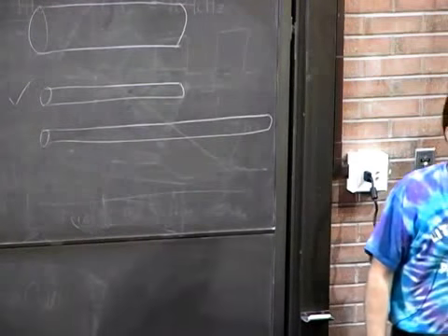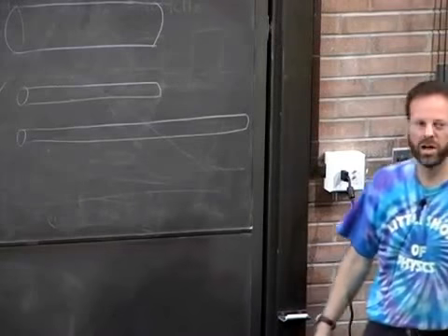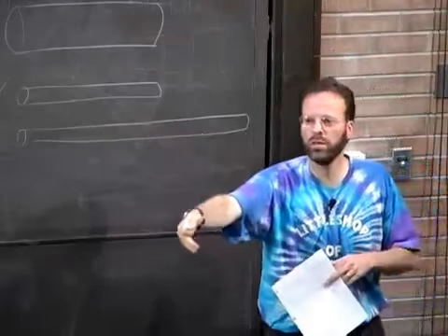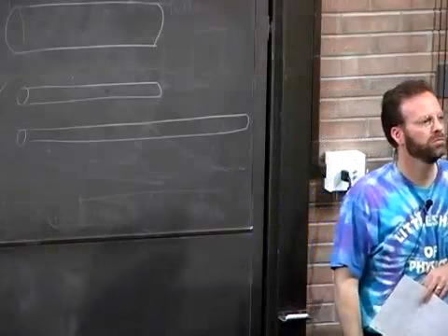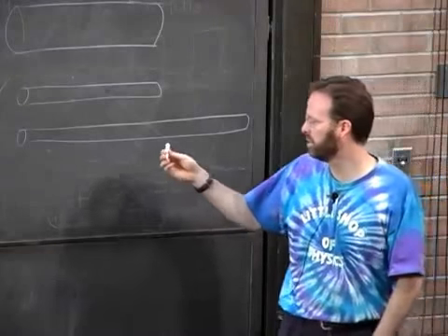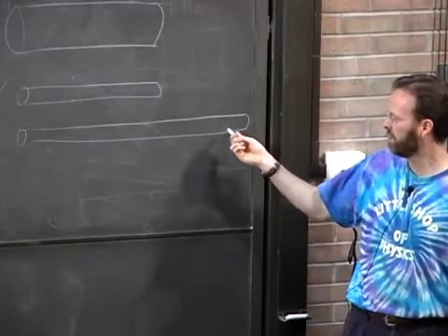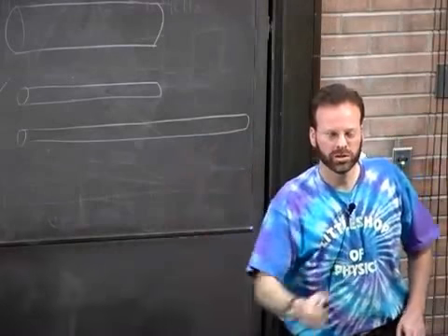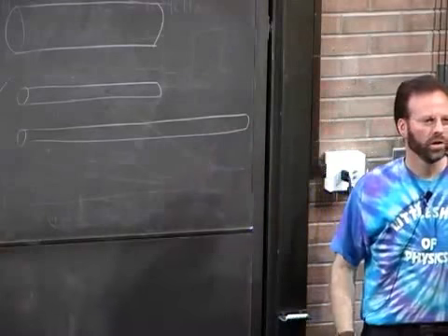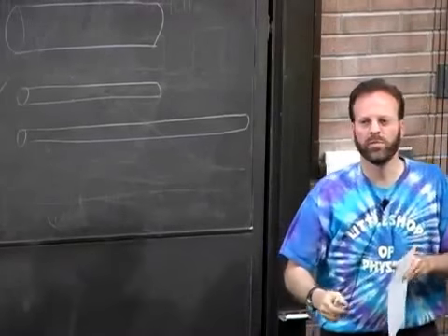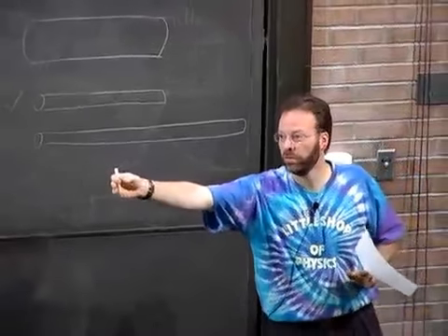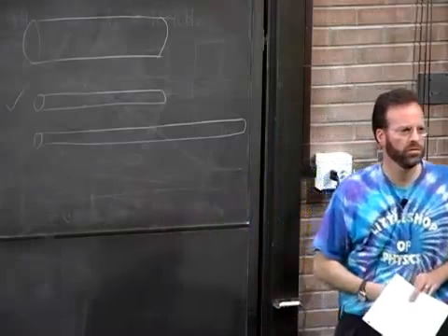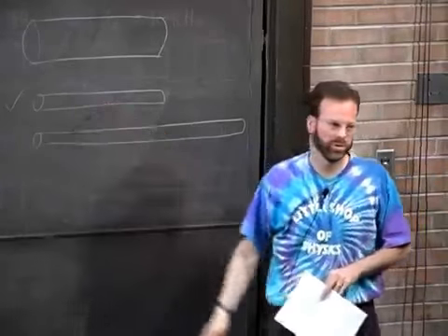I'm hearing more of the bottom, the longer one, than the other. That's correct. If you've got more stuff to go through, trying to shove it through more, there'll be more resistance as well. I hope that makes sense, at least after I say it. Just think of it as ridiculous. You have a mile-long cable versus a little paper clip. It'll be easier to shove it through a paper clip than a mile's worth of conductor. So longer things have more resistance, and skinnier things have more resistance.